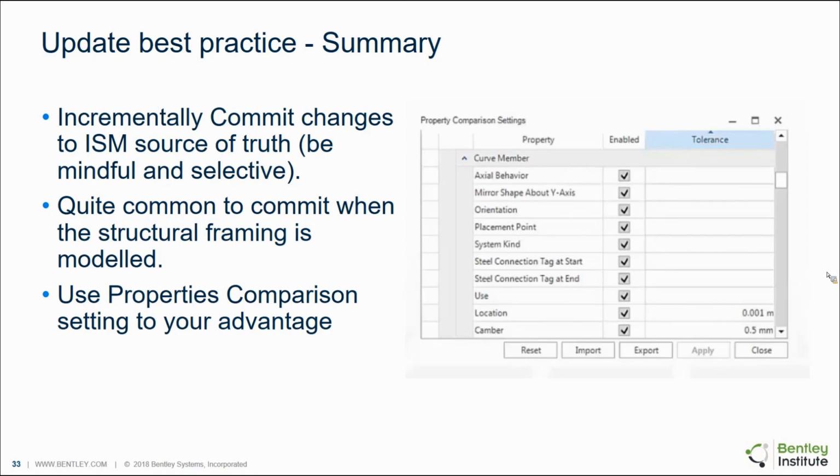And in our latest version of Structural Synchronizer, we have this tool called Property Comparison Settings. What that deals with is a question from the user where everything is blue on update or everything is modified on update. And why that is: no matter how inconsequential the property modified is for an object, it will always appear as blue if it's modified. So if you only care about certain properties to compare, you have the power to control this. So, property comparison settings.